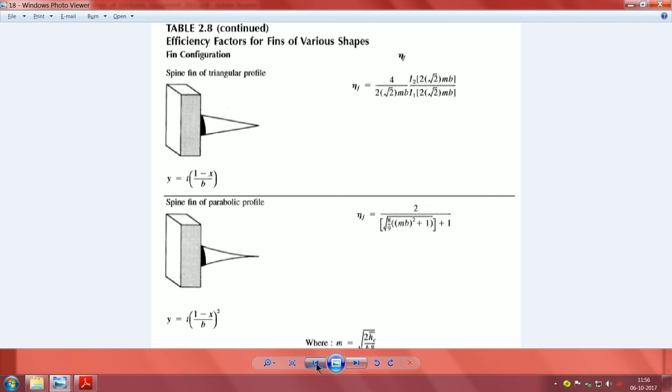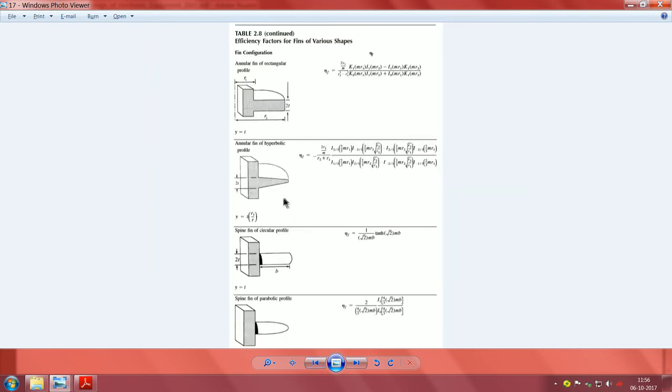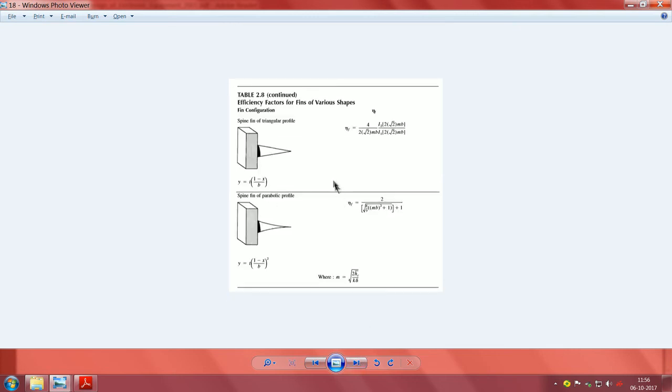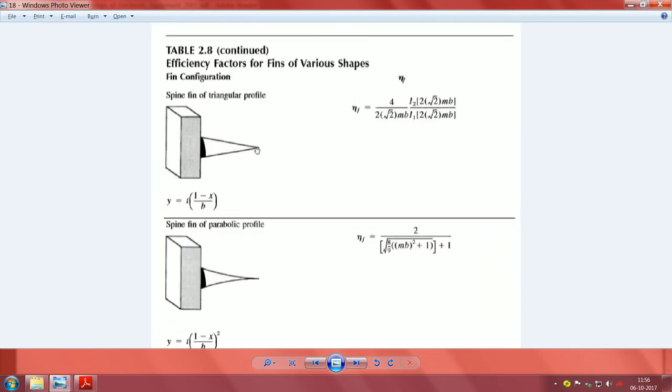The difference is earlier, as you have seen with this annular fin, the heat flow is going on radially, and this is typically what you are likely to find as pin fin heat sinks. But because of the manufacturing difficulty, usually they continue to be straight fins, plus they have a fan on top of it.